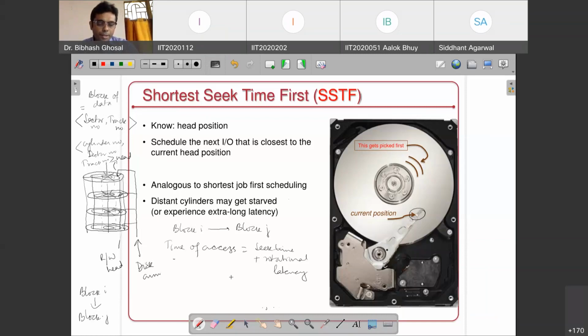And what you get is something like, for a single sector, I'm just giving you a typical order. It's like 10 milliseconds plus 8 milliseconds plus, let's say, the transfer time, that is the time spent in transfer of data, which is about 50 microseconds, and it is of the order of about 18 milliseconds. Okay. So this is the basic idea.